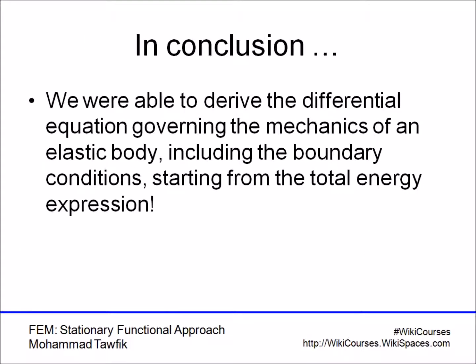So to conclude, we were able to derive the differential equations governing the mechanics of an elastic body, including the boundary conditions, starting from the total energy expression. That's actually the power of the variational methods. If you can write down an expression for the total energy, you can get everything from there.